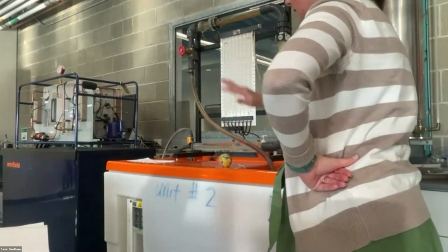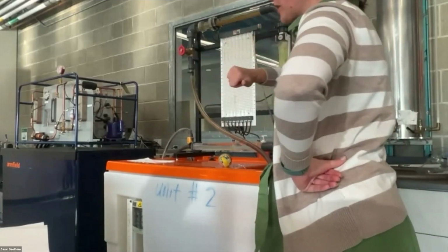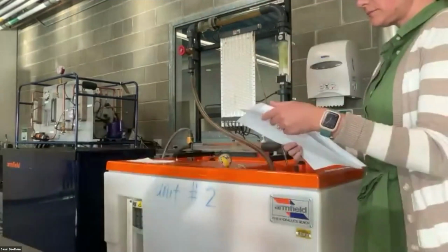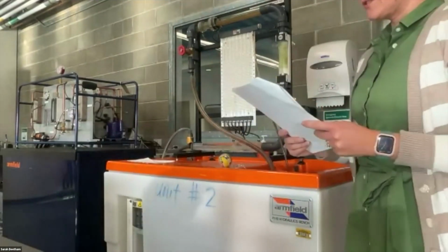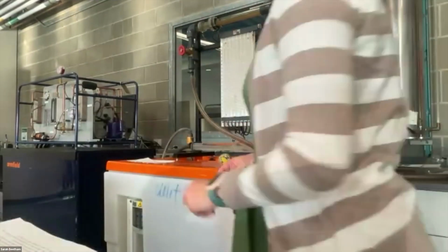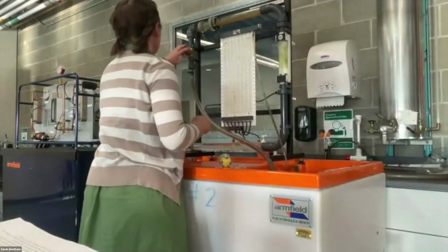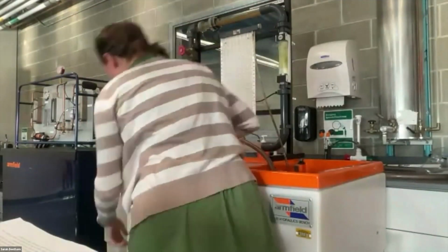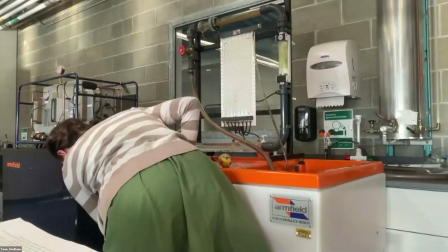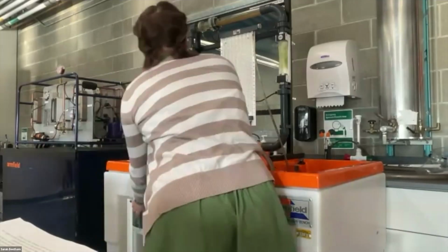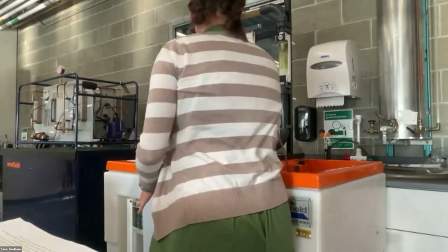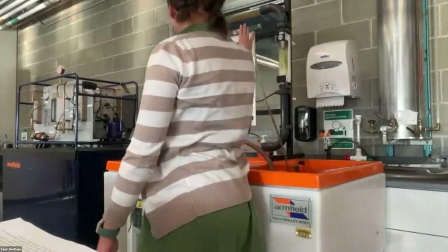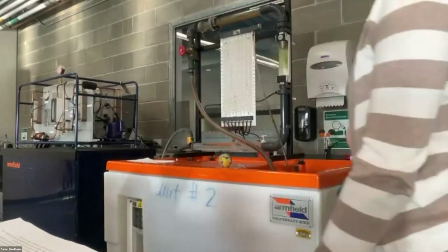So you'll come in, verify that all the valves are shut all the way. And then what you're going to do next is open the flow control valve, so the red valve, and then the bench valve, that's the blue one. All right. And then we're going to turn it on. So essentially, we're putting water through this entire system. We want to work out all of the bubbles in here.